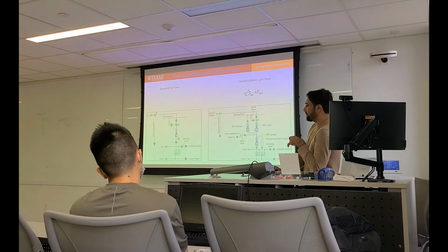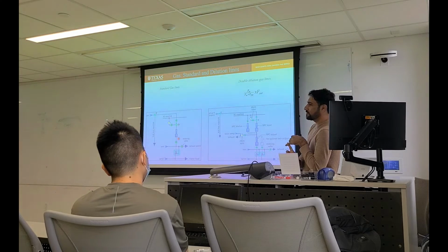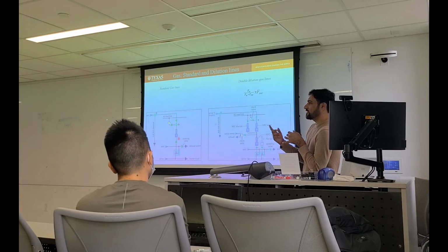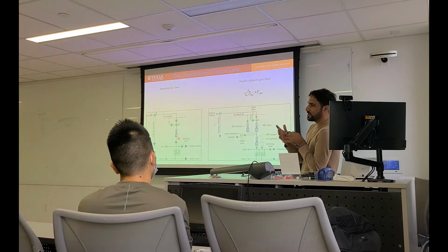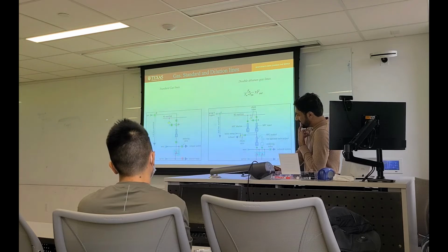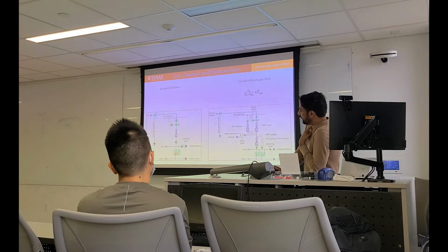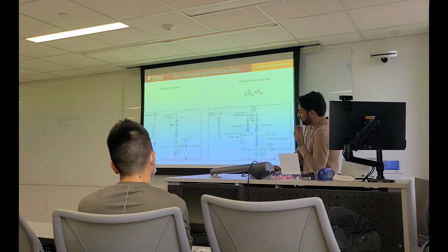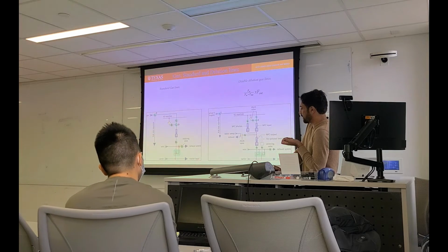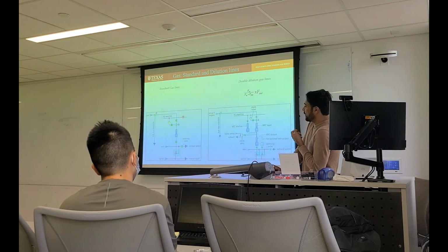Suppose you have an MFC with a maximum flow of 200 SCCM. They have some error, so you cannot use the maximum flow. You should use 190, about 10% below the maximum flow or 10% above the minimum flow. Then it will give a uniform flow. As I mentioned before, we can control the injection manifold to switch our gas towards the reactor or towards the exhaust system.